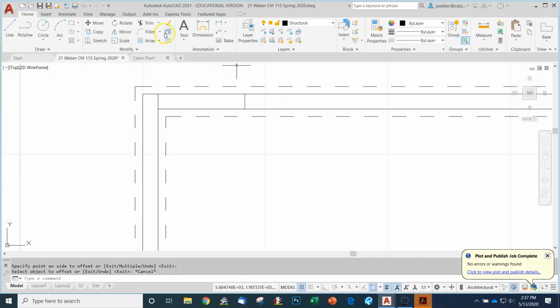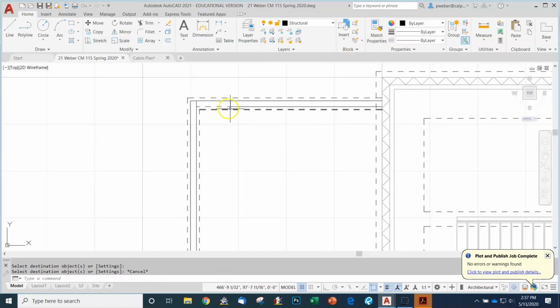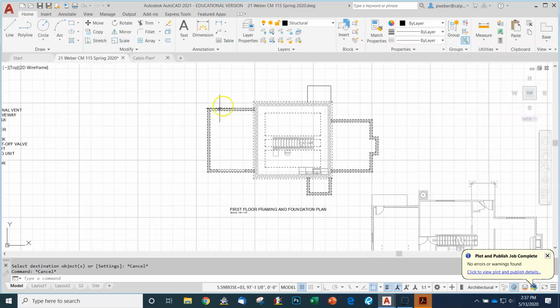Perfect. Okay. Once again, I use the trim command, and I want to trim this to the nearest boundaries. Okay, I'm done. Throw a wall line back in from here to here, press escape, use the match properties, touch this dash line, and touch that. Because again, this is a 2 foot tall stem wall here and here. This is a 1 foot tall stem wall.